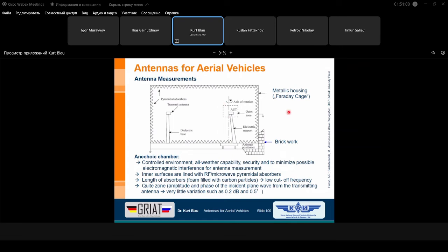But again, in a lot of cases it's a distortion, and the signal strength is not large enough to measure the antenna under test with the necessary dynamic range, meaning the depth of the nulls and so on. It's not sufficient if you use only unwanted signals working at the same frequency from outside.